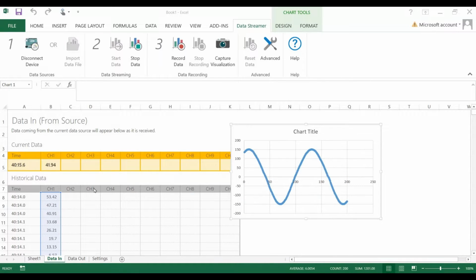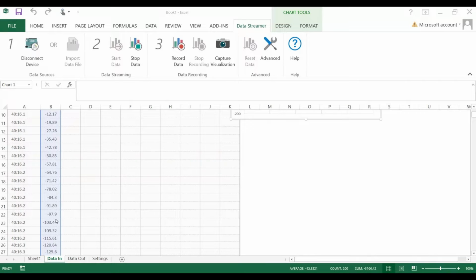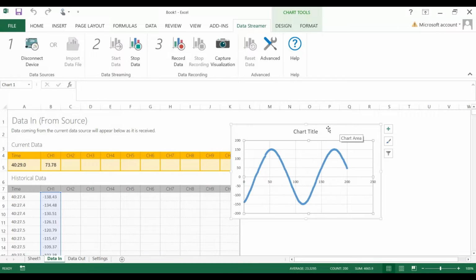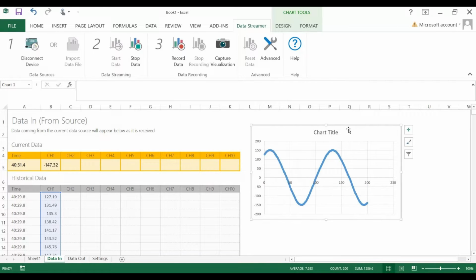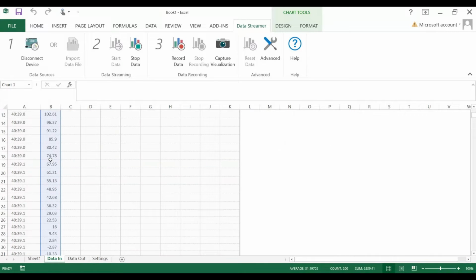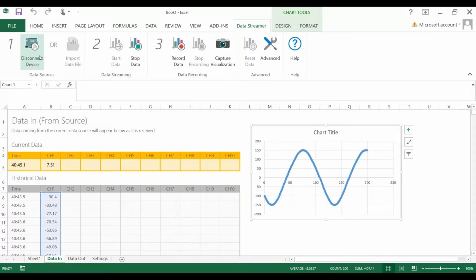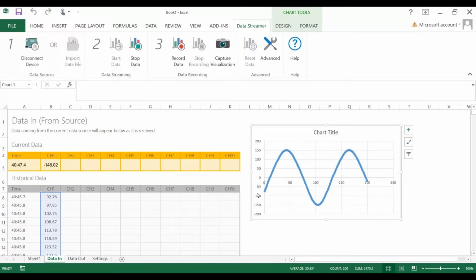As you can see here, we are receiving some data. Yes, from where? It's from Arduino. So in this tutorial, we will learn how to link our friendly friend Arduino to the Excel sheet, and we will learn how to receive the data. You see now, this is real-time data from Arduino through the serial communication.